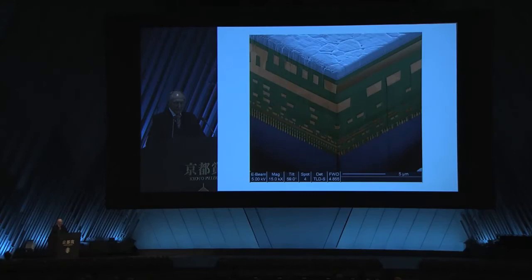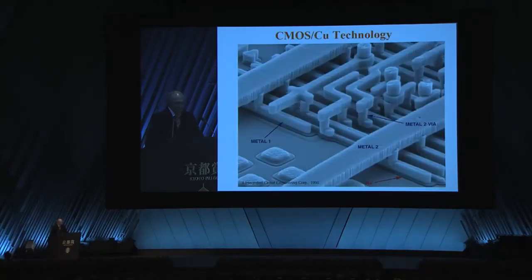This picture shows a highly magnified cross-section along the wiring layers in a chip with the new copper wires first introduced by IBM. You can clearly see the smaller wires in the lower wiring planes and the larger wires in the top planes. Here is a scanning electron microscope picture of some of the lower level wires with the insulator layers etched away to show how wires in one direction are connected to wires in the perpendicular direction. Today's latest, largest processor chips have as many as 14 wiring layers, and the billions of interconnections use a total of about 40 kilometers of copper wire. These wires are truly as important as the transistors in making integrated circuits work.